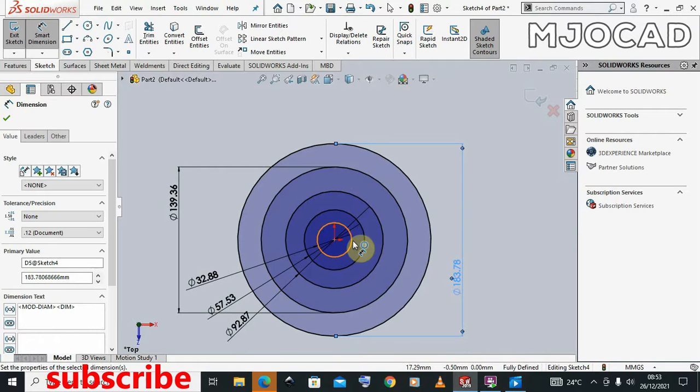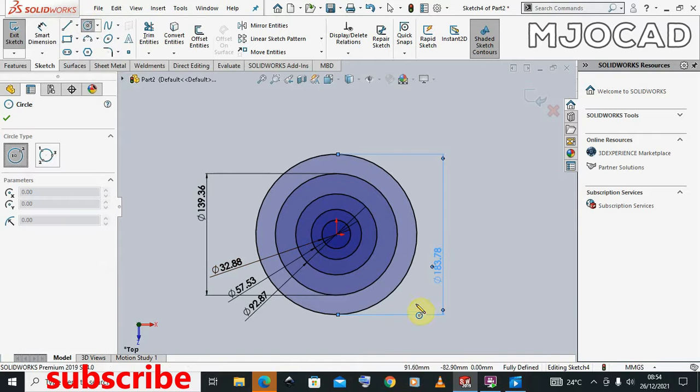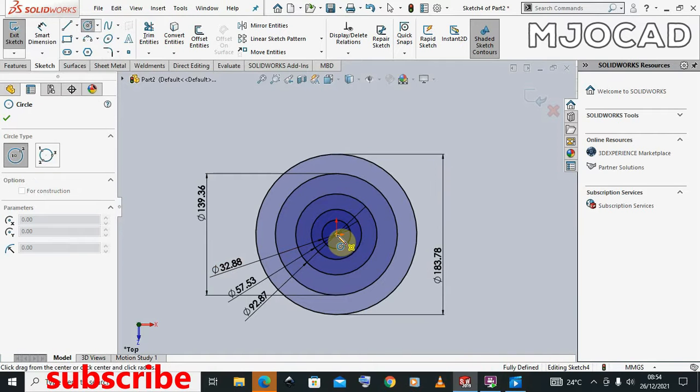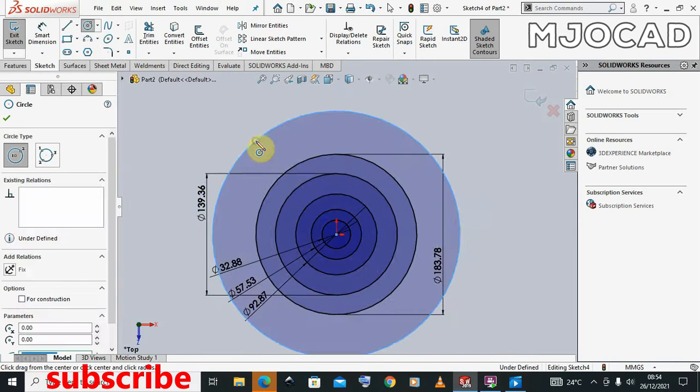Still with this very circle, I'm going to use it for the perimeter circle. Perimeter circle means that you have points along the circumference that you're using to define the circle. You don't have the center and the point outside like we've been doing in the first command. Realize that in the first command you do the click, which is this first point here, then as you drag you do the last point, which is this point on the circumference here.